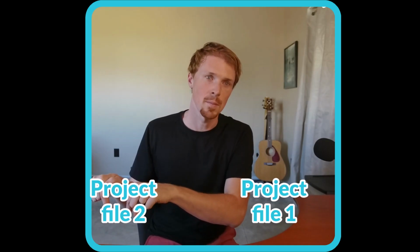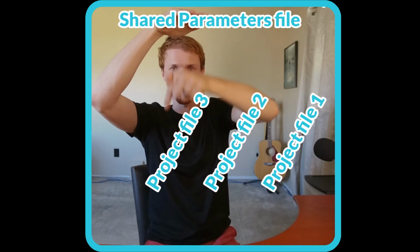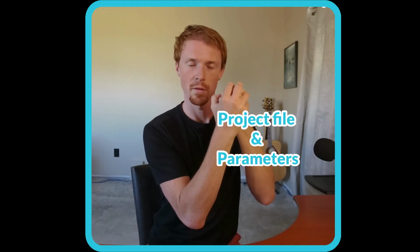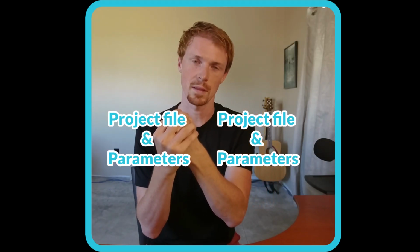They live in each file where they were made. They therefore cannot go from a project you are currently working on to another project you're working on because they are inherently embedded within that file. So keep that in mind. Shared parameters, if we think of like a tree graph, can be connected to many different project files, whereas project parameters, or family parameters for that matter, can only be held within that one file, and they cannot go from one file to another. They are unique.